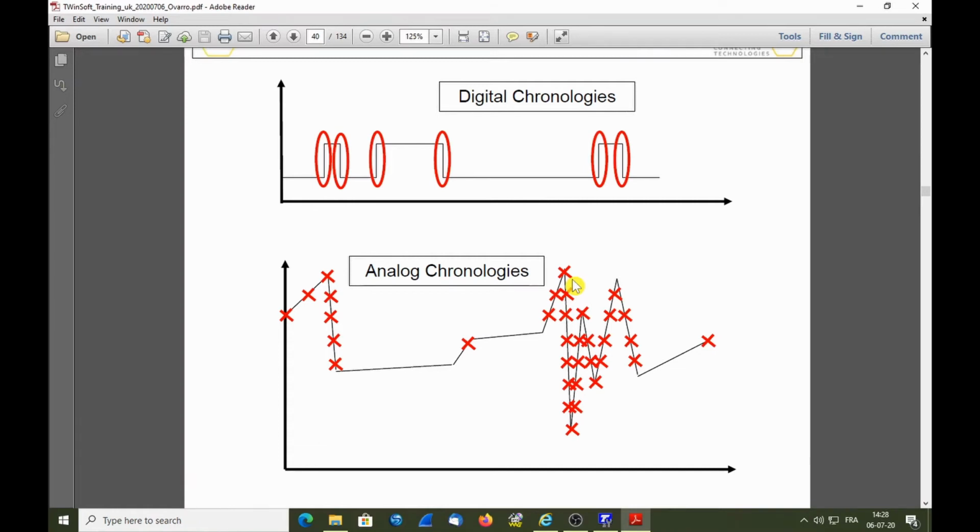Chronologies constitute recording on event, so the variation of the tag will determine the moment when the tag is recorded. If we speak of a digital tag, it's the changing from 0 to 1 or the changing from 1 to 0. You decide which event you want to record, variation from 0 to 1 or variation from 1 to 0. You can define that for each tag individually, of course.